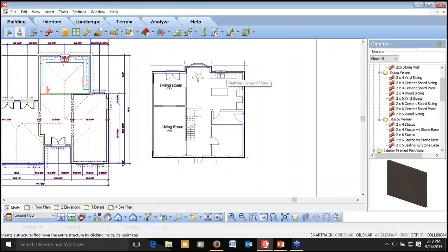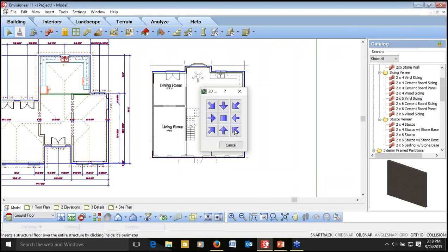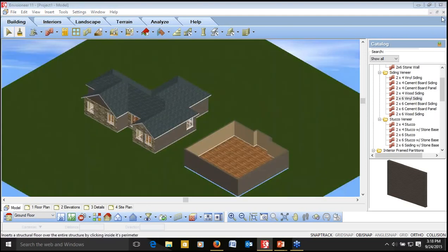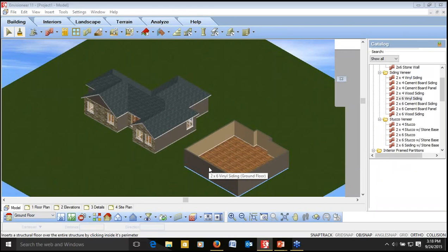Those are 3D walls, so if I look at it in 3D, I already have the bill of materials now for those walls. So if you're getting your designs from an architect or an architectural designer, you can bring in the PDFs that they provide for you, or you can bring in the actual DWG file. They're both going to come in as flat 2D line drawings. But from there, just as quickly as I did there, tracing over top of it, you can get your bill of materials because you've just built that 3D model and it knows the elements that are being used in it.